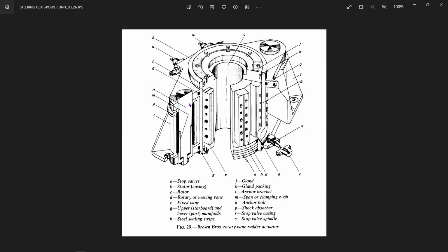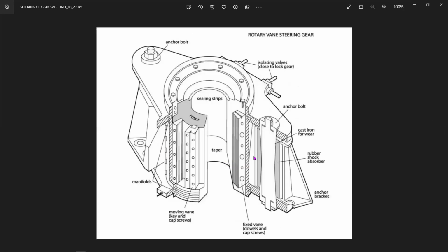Okay, you do not have only two pins. You can have a full bolting system arrangement also. This is the older mechanism where you've got a two-pin anchor pin arrangement like that. Okay. And this is a better diagram of the same. So what you have here, rotor and stator, that has already come. But what you have here in the center is this entire housing connected to the stator, and here you have rubber, which is again a shock absorber connected to both sides of the anchor pin.